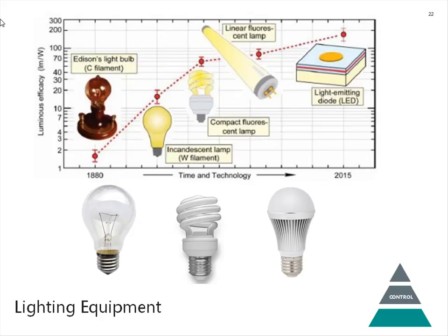It's a pretty linear story in terms of moving from incandescent, which is more efficient as a heater than it is as a light source, through compact fluorescent to today's LED fixtures. You can kind of see how the efficacy has increased from maybe 40 to 70, let's call it, for compact fluorescent, up to close to 200 lumens per watt for LED. It's a very simple fix for improving the lighting efficiency in your home.